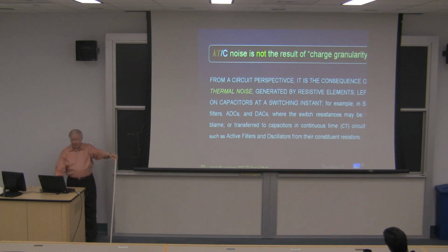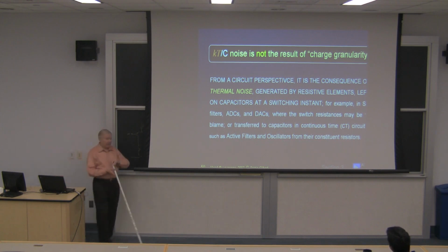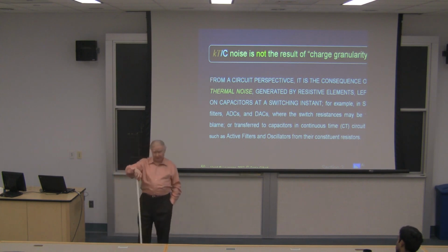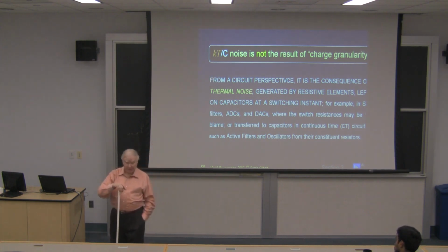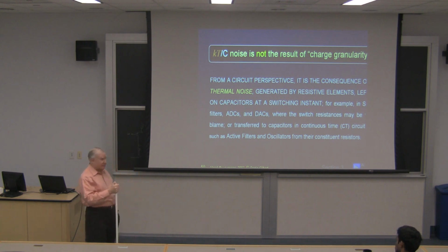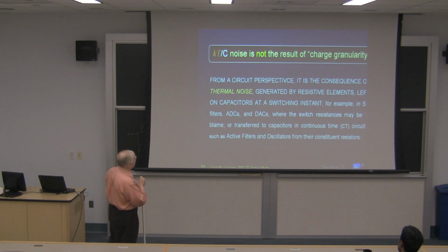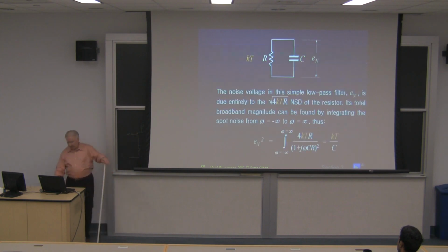And in spite of the fact that it's a common metric, because it says to us very plainly that if you want a circuit involving lots of, say, switched capacitors to be low noise, then you have to use large capacitors. There's no way around it. That's the nature of noise. It doesn't give you much room for messing around. So we're going to ask, why does that happen? Where's it really coming from?